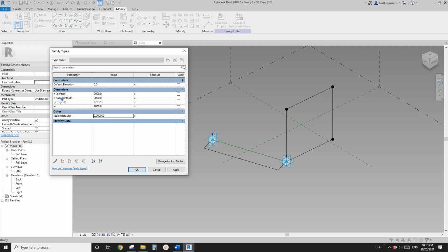Now we can type in height. The actual height equals height base plus a bracket, reporting parameter, the distance between point 1 and 2, times the scale. And that's it. Now if I click OK, because currently the scale is 0, so 0 times RP will always be 0.